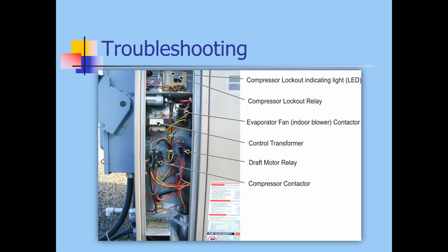Be familiar with the wiring diagram so that you can easily identify any of the components and then apply that to the schematic diagram for troubleshooting which operation is not working properly. And remember, start simple. Check the connections. They might vibrate loose over time, so it's always good just to make sure all the screws are tight, and keep in mind that the problem might not be electrical.